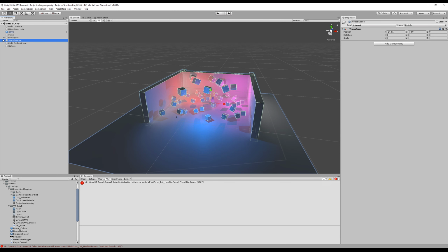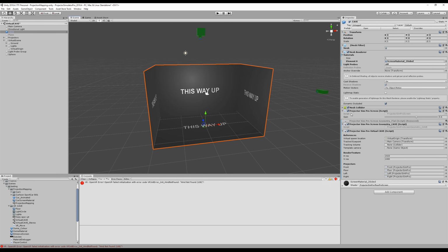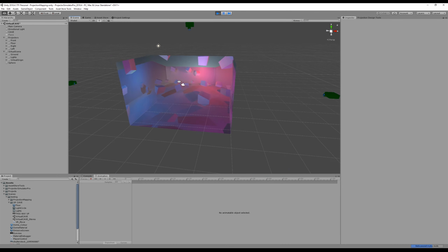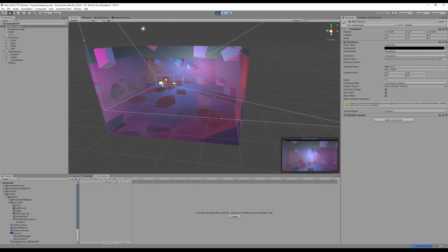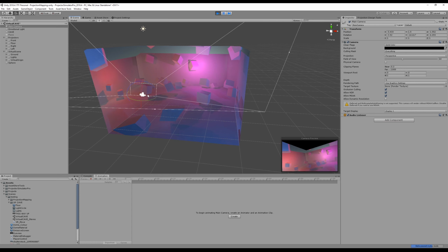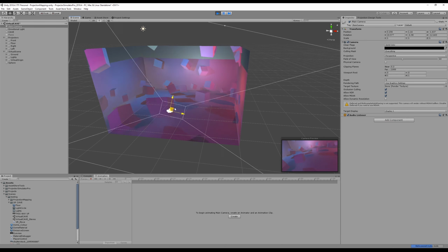This virtual scene has a game object inside it to act as the spawn point for the cave view. I can then tell the virtual cave component where the spawn location in my virtual world is, and which object to track for the perspective correction, which is normally your main camera. I then tell it which projector is aligned to which face. Now when I hit play, the virtual scene is projected onto the cave, and you see the images aligning at the edges. When I move my camera around, the virtual views are updated accordingly so that the perspective always looks correct from the eye point.